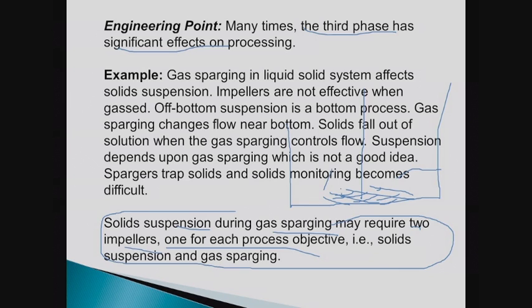So he had good flow with simple liquid here, perhaps. But when you added in the solids, sand dunes started to form because the sparge ladder was trying to sparge gas against rising sand dunes. So it may have eventually come out to, looking down on this, a whole sanded-in region and maybe one or two or three holes operating, letting this gas out.